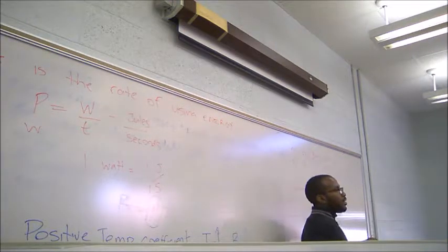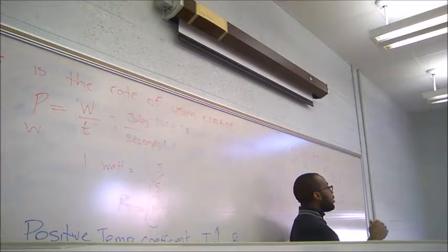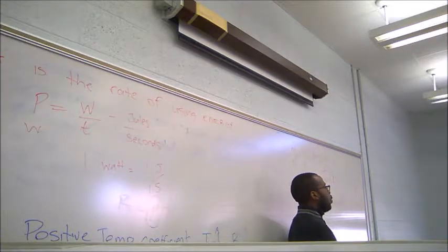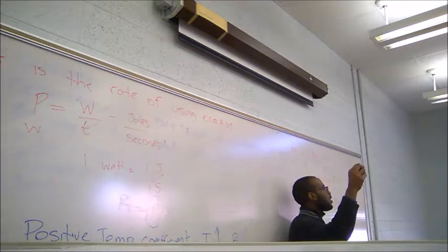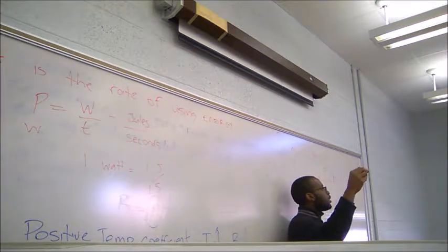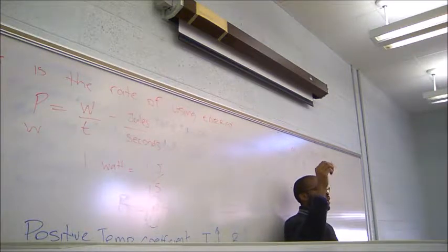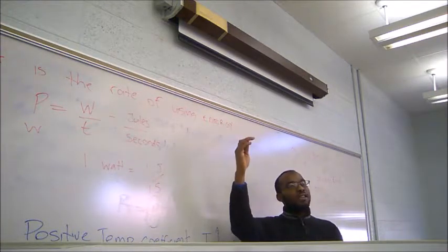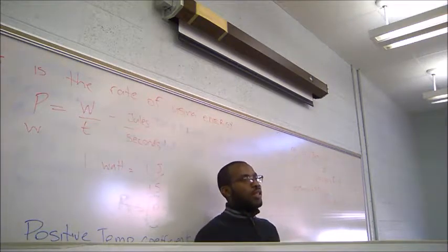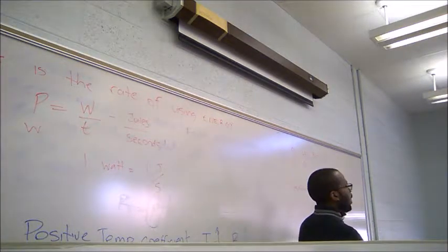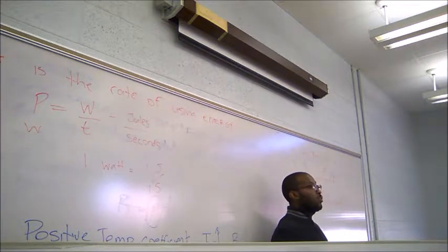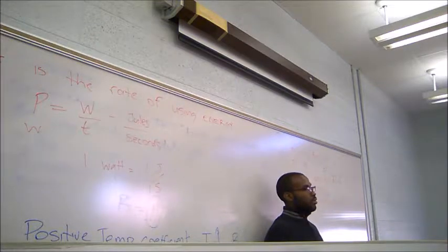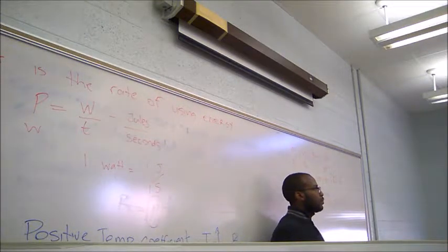313.5. Okay. So again, the tolerance tells us, based on the errors in the manufacturing process, what percentage we can expect the measured value to be. Because nothing is perfect. No process is perfect. Any component that is manufactured has some error. And so the tolerance is accounting for the error. It's telling us the value can be either 5% above or 5% below. Now again, there are different tolerances. We have 5%, we have 10%, we have 15%, and we can have as accurate as 1% as well. Any questions about this?